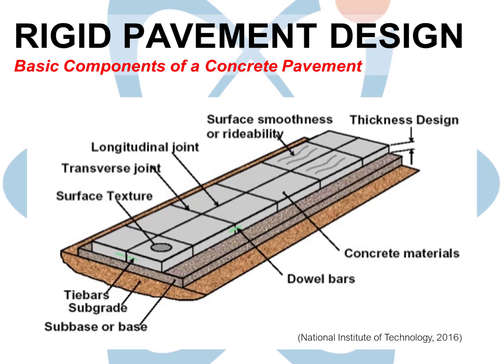How smooth the pavement feels is also a function of how fast the vehicle is. A pavement that feels fine at 60 miles an hour in a car might feel completely unstable at 150 miles an hour in a jet. Joint placement and performance are very important to maintaining a good surface smoothness, but it's just one part of the design and construction of a successful pavement. The combination of joint design and placement and what kind of surface texture is constructed can make or break a pavement design, regardless of the structural performance of the pavement.